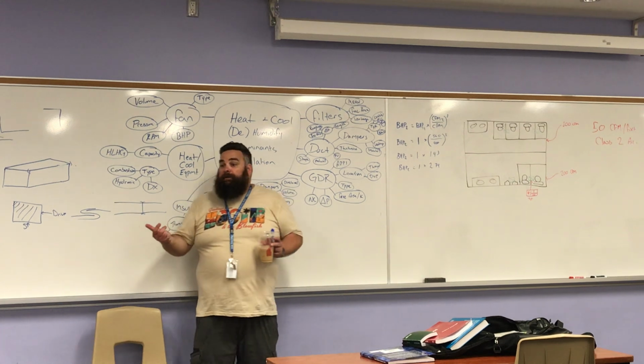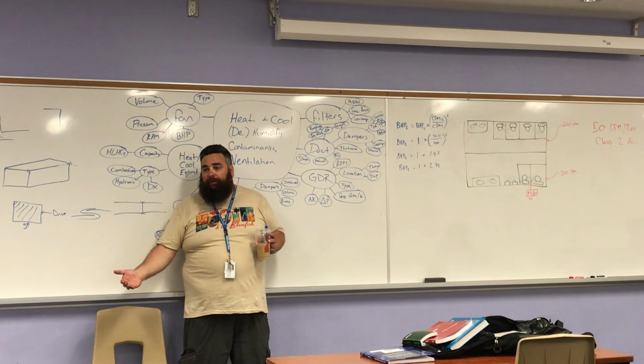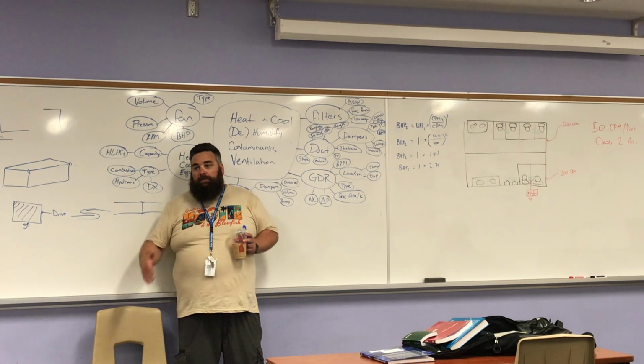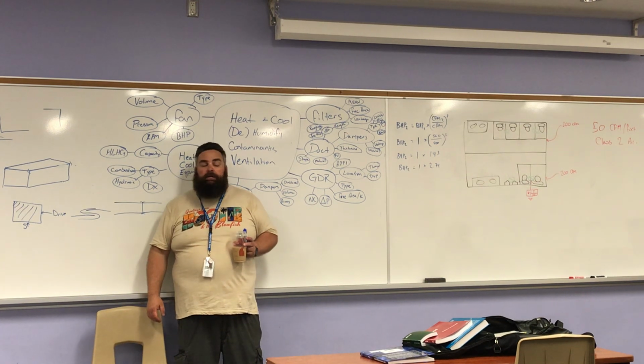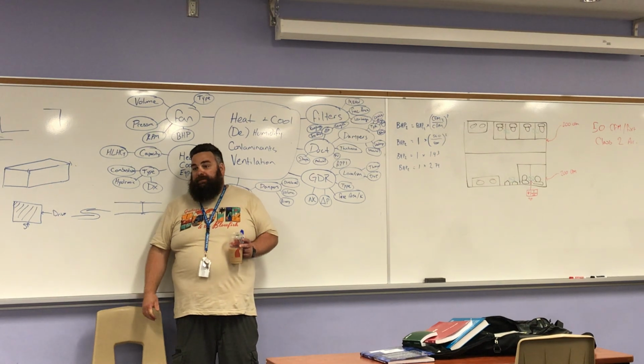So I wanted to make sure that these dogs were going to be safe. So we had like 13 tons of cooling in this place. The original rooftop unit was like 5 tons of cooling. So substantially higher. Turns out they didn't have sufficient power for the things. So we had to do load shedding and diversification.